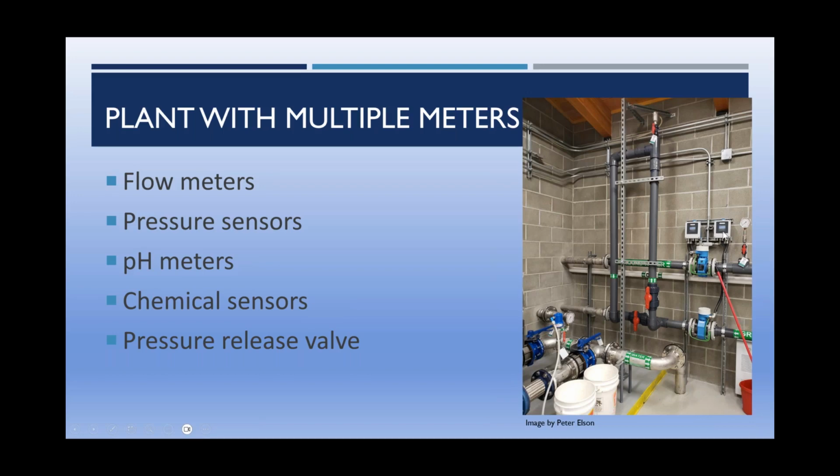That's why there are 2 flow meters and two display meters. But this is actually fairly similar to a lot of the setups for chemical sensors and pH meters. They'll also have the sensor actually in the pipe, but the actual readout will be on a panel above it, pretty much like these two up here.